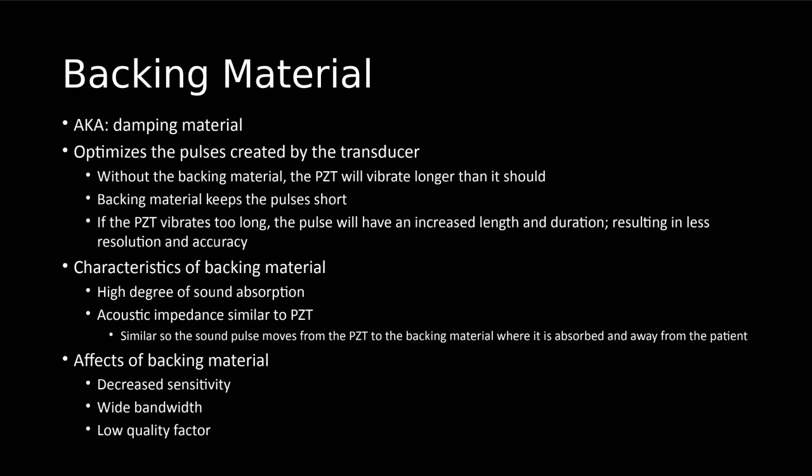But when we're adding this backing material, we are affecting other things negatively. So we're decreasing the sensitivity, right? So we're basically saying you can't be as strong as you want to be because I'm going to dampen you. So we're having a decrease in sensitivity from this backing material. We are also having a wide bandwidth.